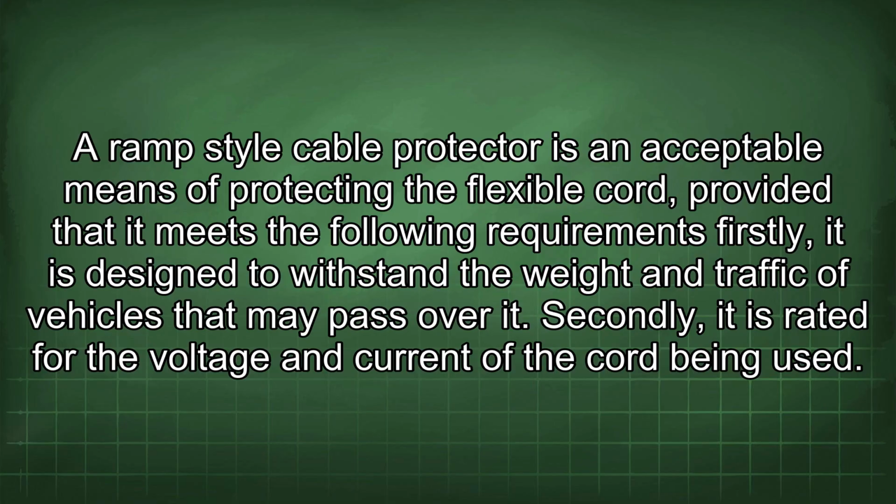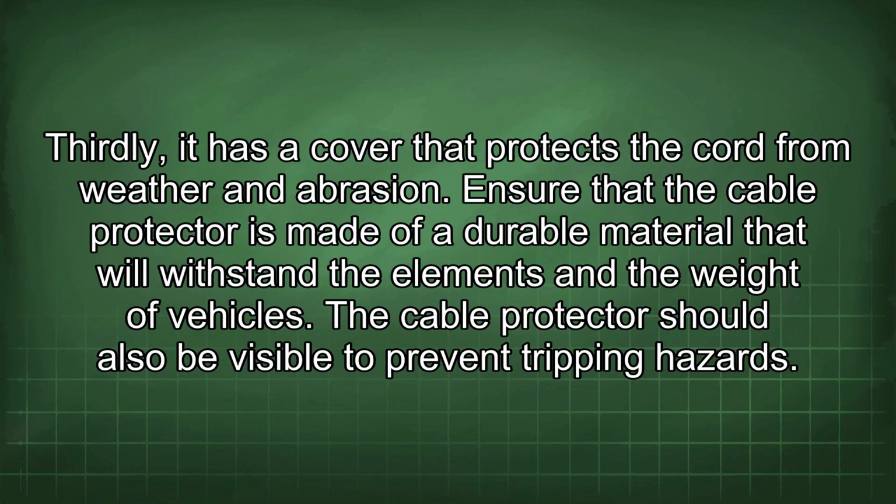Firstly, it is designed to withstand the weight and traffic of vehicles that may pass over it. Secondly, it is rated for the voltage and current of the cord being used. Thirdly, it has a cover that protects the cord from weather and abrasion. Ensure that the cable protector is made of a durable material that will withstand the elements and the weight of vehicles. The cable protector should also be visible to prevent tripping hazards.